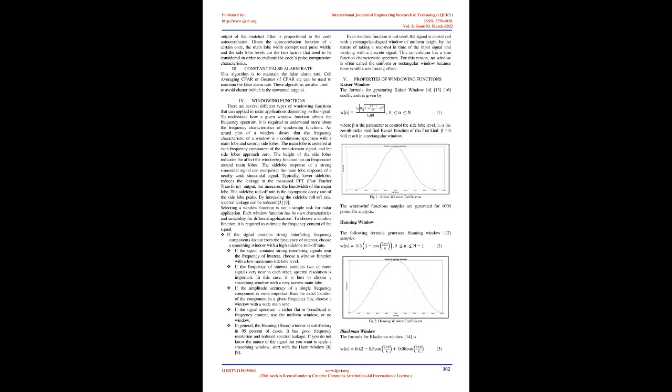For a simple rectangular pulse, the bandwidth is just 1/t, where t is the pulse duration. However, by manipulating the amplitude and/or phase within the pulse, its bandwidth can be altered without changing its duration. In other words, the radar resolution can be changed independently of the average transmitted power. This manipulation of the transmitted pulse is known as pulse coding, or in some cases, pulse modulation.